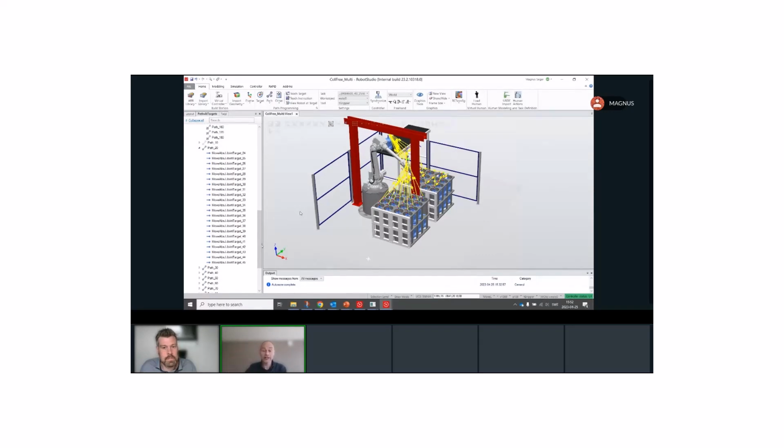in sequence like this. But we are also looking into how we can plan in linear space, and also how we can inject, of course, this is just a pure motion, what will happen as well when we come to the actual positions, and so forth. So we can have some post and pre conditions as well happening. But right now we plan in joint targets to avoid singularities, and so forth. So this is the outcome of the automatic path planning.